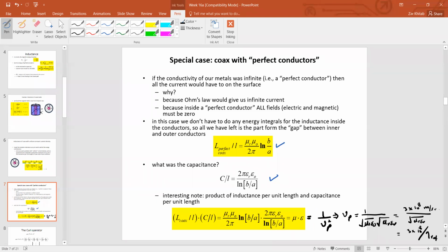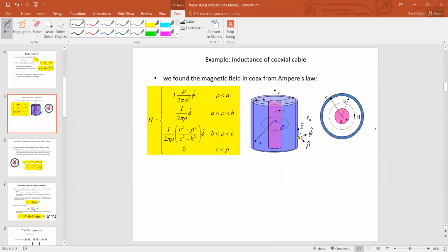The mu r and epsilon r, or the refractive index, is of the material used between the two conductors. That white plastic sort of material which you see in the coaxial cable is a dielectric which you use in the coaxial cable, for example, Teflon. This will lead us to the characteristic impedance, which we have not found yet, but we will be able to calculate the characteristic impedance of the coaxial cable using all these terms.